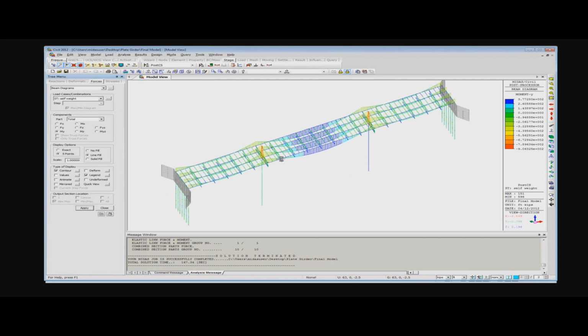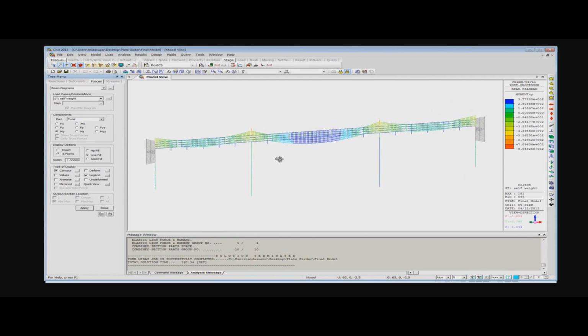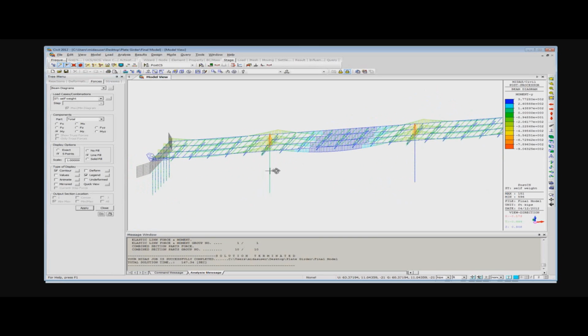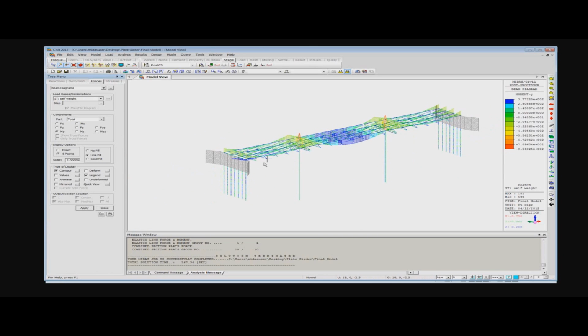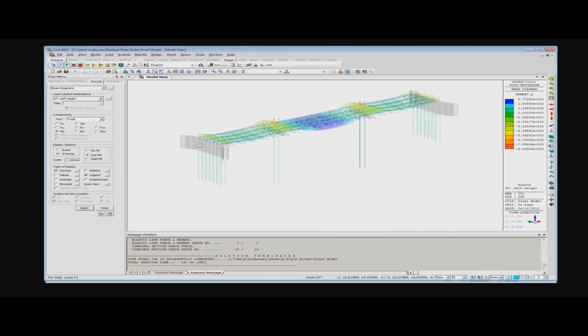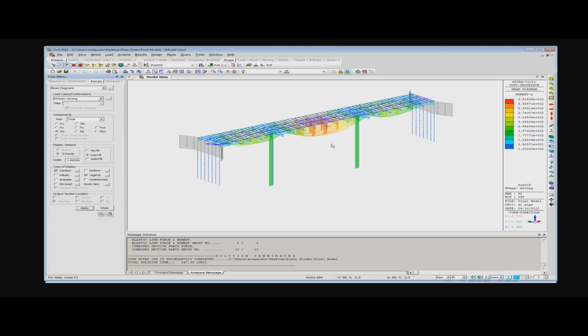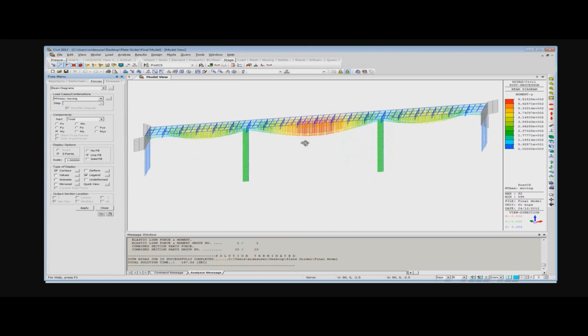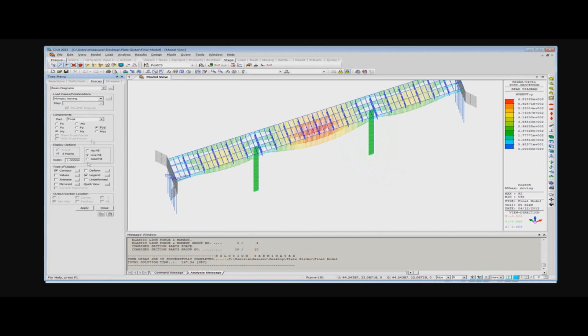Okay, so you can see that bending moments are shown for all elements, which are actually beam elements. Now the abutment is created from the plate elements, so we don't have any result on them, but we have to go to the beam results and check those out. So okay, for the moving load maximum, you can check this out and see the results for maximum bending moment, or you can check it for the shear forces.